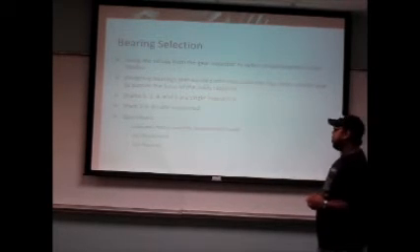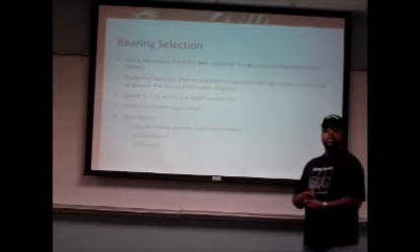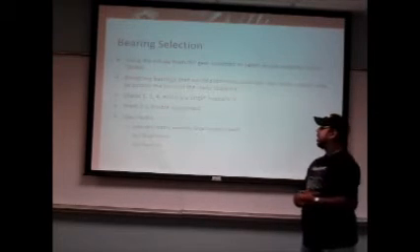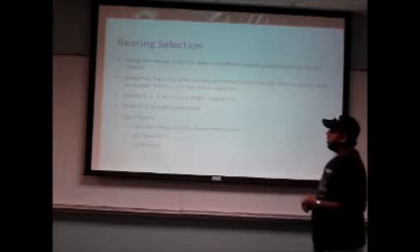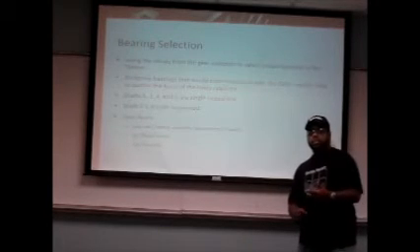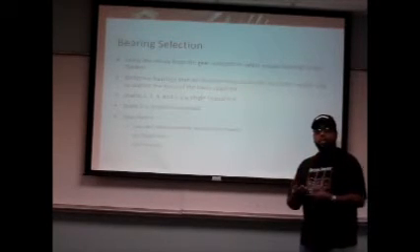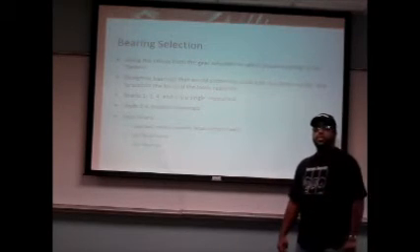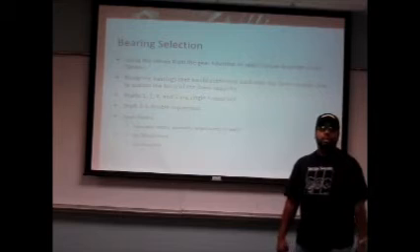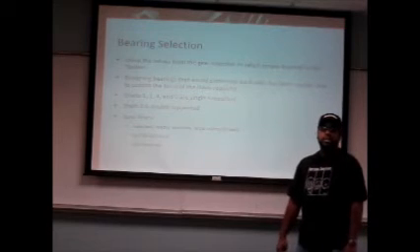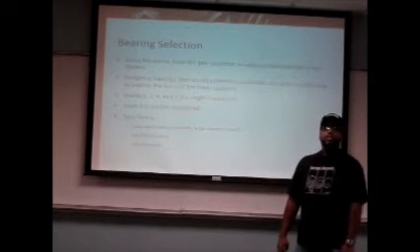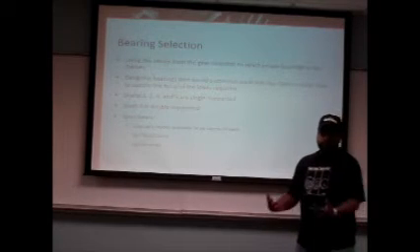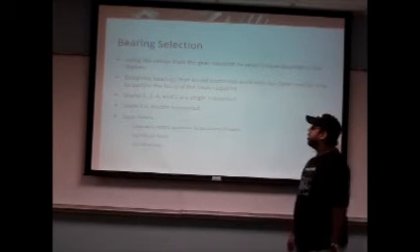Based upon those forces and the equation for the C0 value in the textbook, we were able to define the C0 value and then use that value coupled with the pitch diameter of the gears to select a bearing that would not exceed the pitch diameter of the gears, but at the same time would withstand the radial and axial loads as combined in the C0 value.